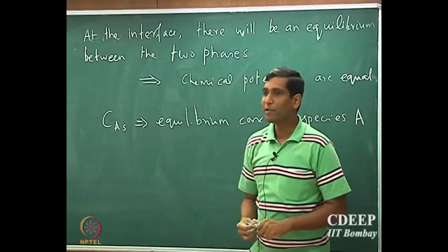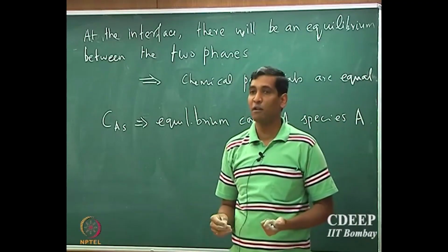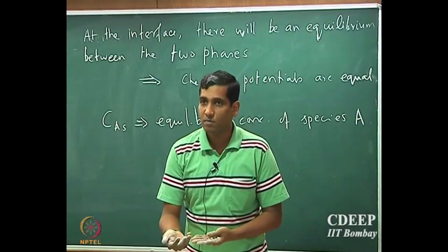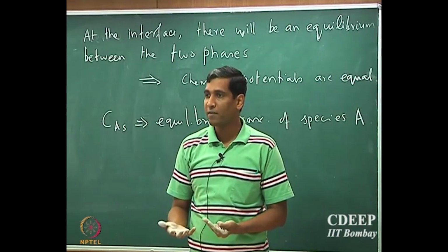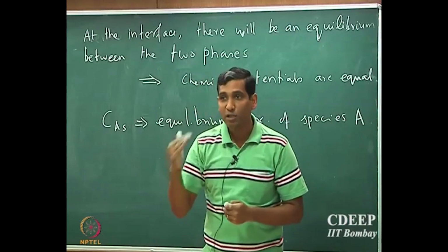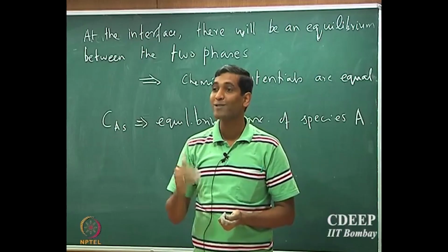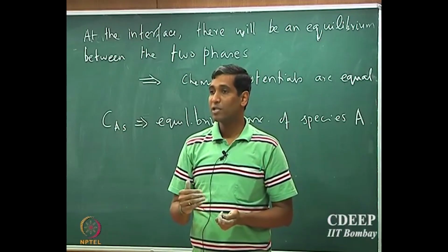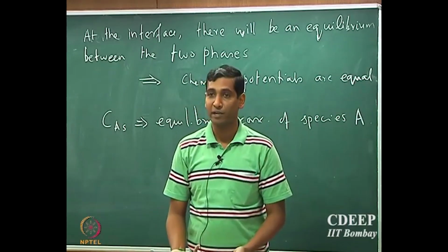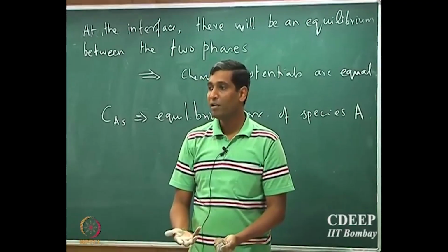Okay. Now what it means is that unlike in the case of heat transport, where you supply heat, the material is going to have a certain capacity, so it's going to take energy and the temperature is going to increase. That's not the case with mass transport. So you always have the issue of what is called saturation. There is only a certain amount of solubility of a particular species in a given medium, right? You cannot add more species to it if you are above the solubility limit.